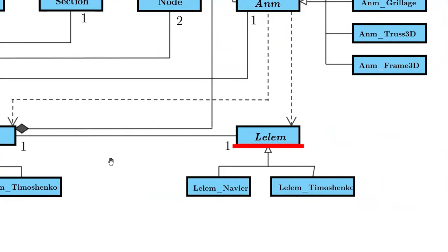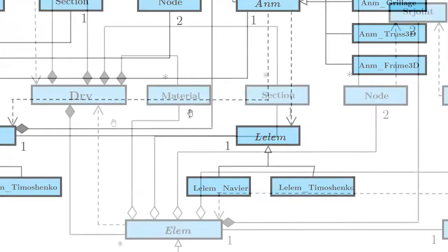The LESM class is the load element class that defines an element load object that's responsible for defining the response of a linear element to load effects, such as the computation of element fixed end forces, element equivalent nodal loads, and element internal displacements. Also, two different types of flexure behavior are considered, the Navier and the Timoshenko.